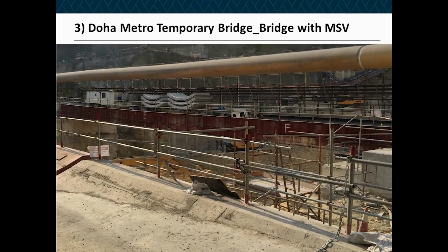The bottom part of the box girder was only 600 mil deep. The whole depth was around about 1.4 meters, something like that. So we were pushing the L over 20, the span over 20 limits that you normally associate with that kind of bridge and that kind of span. But deflection was not a criteria for the MSV. They were quite happy with it deflecting. It was only during the tunnel boring machine going across that the controls were quite tight.